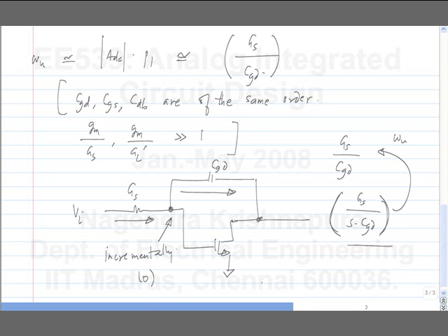Now, under the assumptions we made, the single transistor also behaves similarly. What did we say? We said that the high frequency pole is at very high frequencies and that the DC gain is significantly large. So what does it mean? For any particular value of output voltage, or any incremental current in the transistor, the incremental voltage at the gate source is rather small.